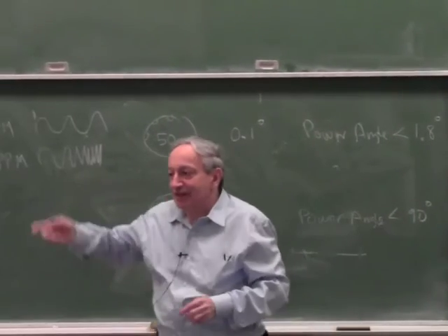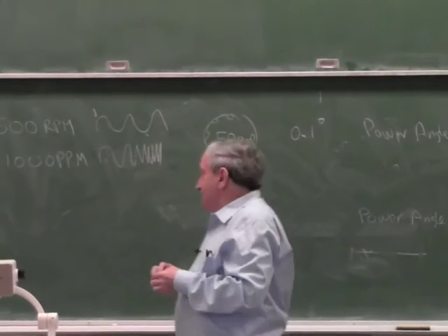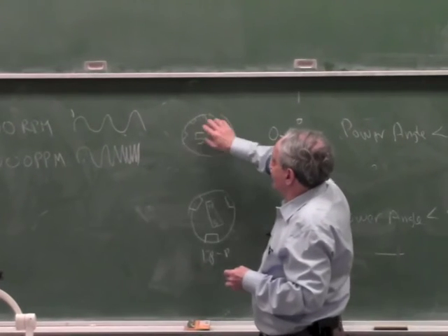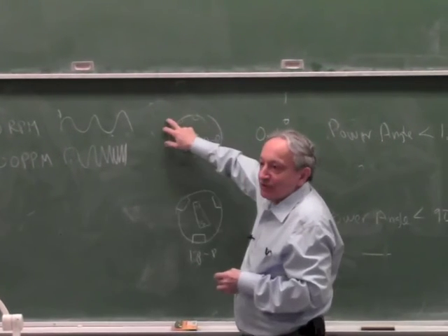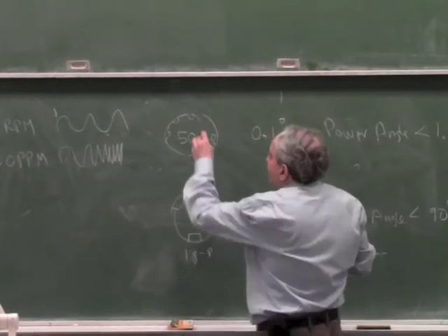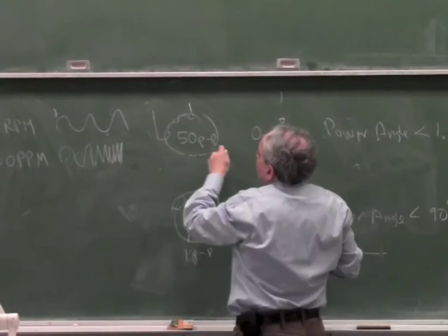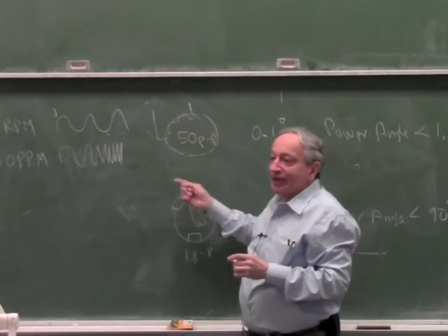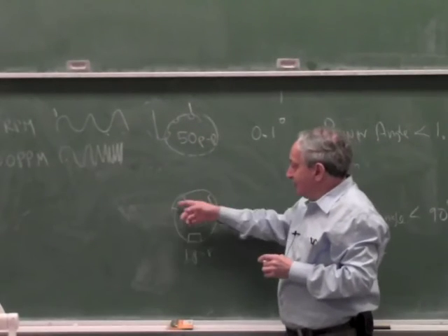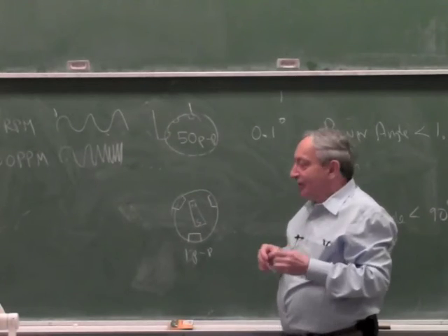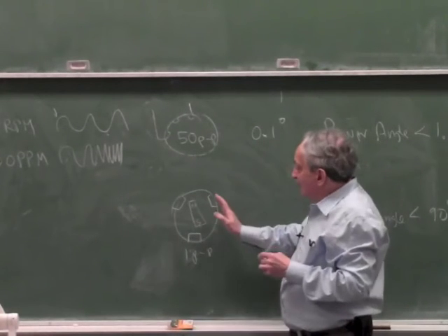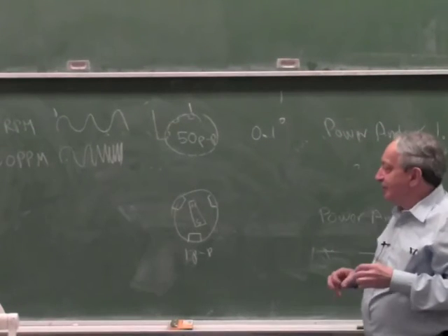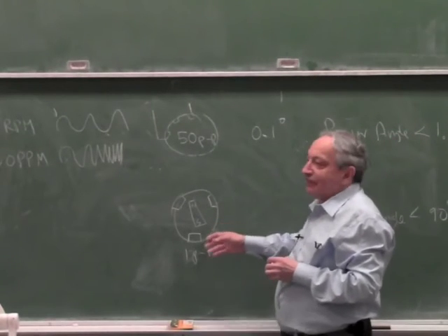If the field is running fast and the rotor is lagging, it also has fewer coils, less inductance. Because remember, if you have 50 pole pairs, you have to have 50 sets of coils which are wired together, because at the end you only have two leads or two coils coming out. So at the end the stepper motor looks like two groups of coils, but they have many windings inside. Now here you can put fewer windings, you only have one set of coils, so there's less inductance, and you're allowing it to drag behind a lot more. So for all kinds of practical design reasons, this motor can run very fast.